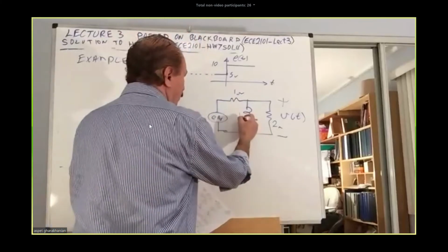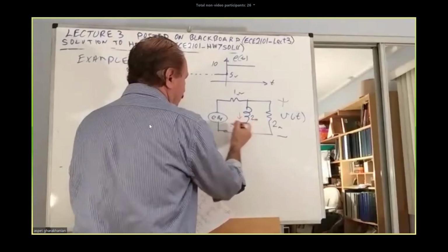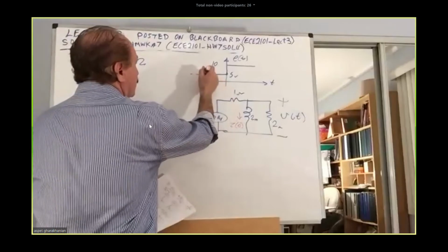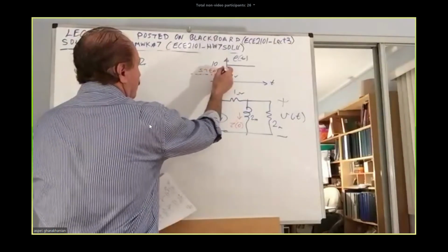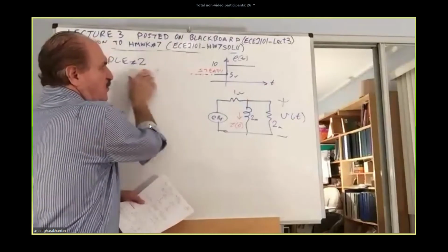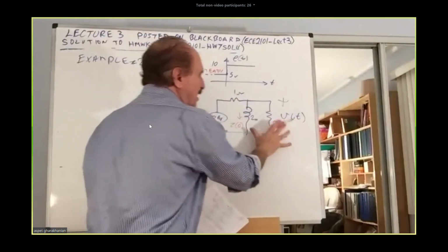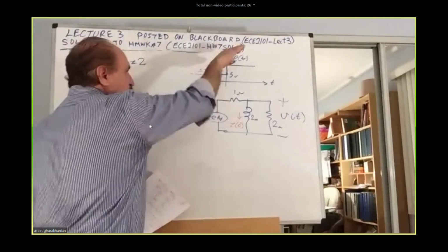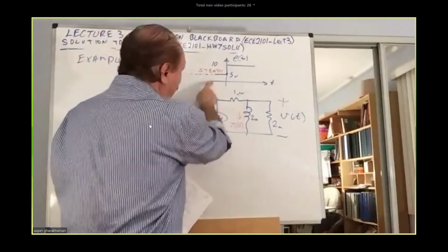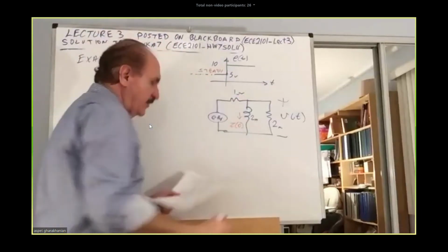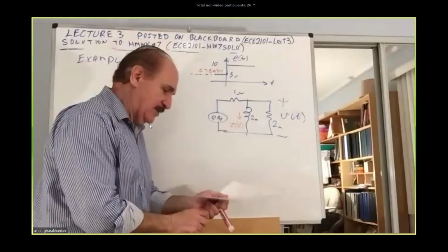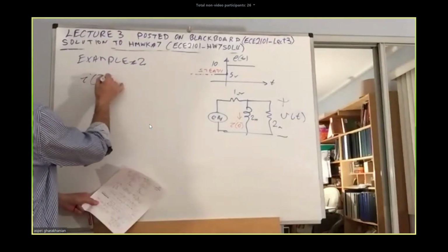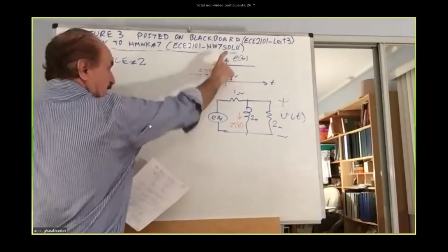First thing to do is, what is I of 0 minus? We need to calculate the I of 0 minus. So here, steady. That 5 volt has been here for the longest time, so everything has come to rest at that point. Then suddenly that 5 is stepped to 10 volt. The 5 volt steady voltage there sets an initial current in the inductor. So we need to evaluate that. I of 0 minus needs to be calculated. This is just before the change.